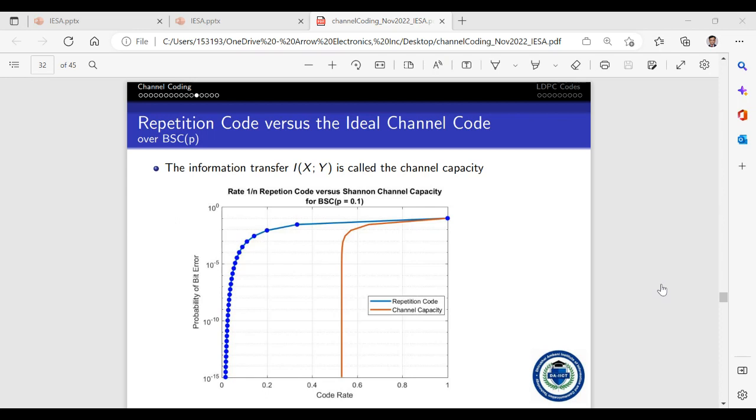The ACM throttles down the spectral efficiency, and so as an end user, your link still survives. It doesn't crash, but the efficiency will go down. So the answer is that the range of spectral efficiency that is achievable has become much larger in 5G, and I will elaborate on that tomorrow when we go over part 2 of my presentation.